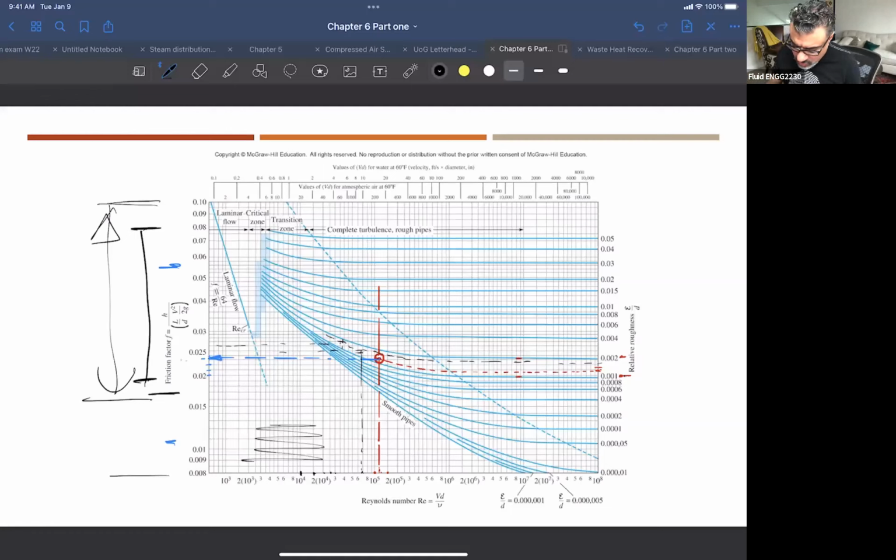So that's why, for most typical cases, there are a lot of standards in engineering applications. For example, velocity in most pipelines is between 1 and 2 meters per second, something like that, right? It doesn't mean that it's not going to be 5 meters per second at some condition or some system. What I'm saying is most typical velocities are 1 to 2, 3 meters per second. Friction factor is between 0.02 and 0.03, something like that. So try to use some numbers around that.